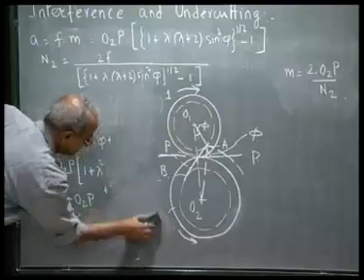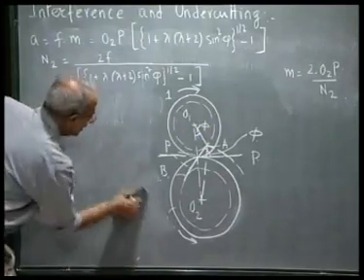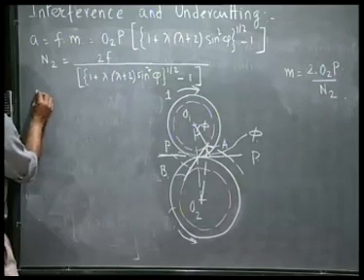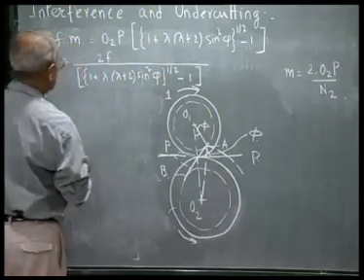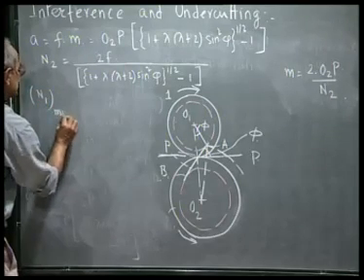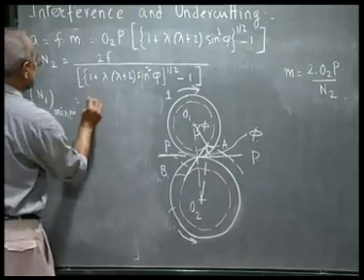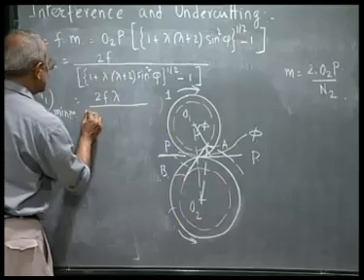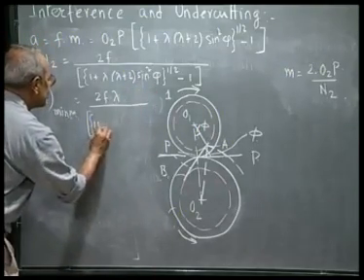We have considered the situation where interference just started with the pinion, and we would get this expression for N2, which means if I multiply by N1 by N2, which is nothing but lambda, N1 minimum, the tooth on the pinion, we get 2f lambda divided by this expression. The denominator remains the same.